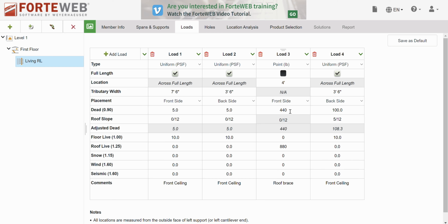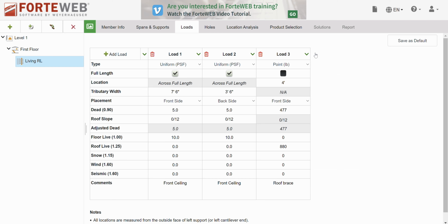That's what I did. So I'm going to take 440 with my calculator that I have, that you should also have: 440 times, let's see, we're doing an addition of 8.3%, so we're going to multiply by 1.083. We get 476.52. Go ahead and round up to 477. Perfect. So I actually have 477 pounds of dead load there. Boom, good to go. Delete this because I don't want it to actually be there. I just use it as a tool.